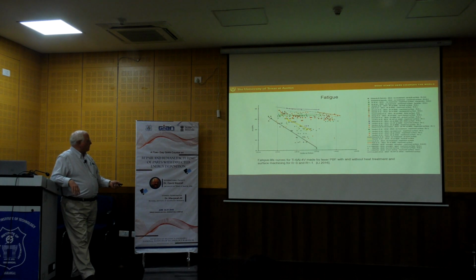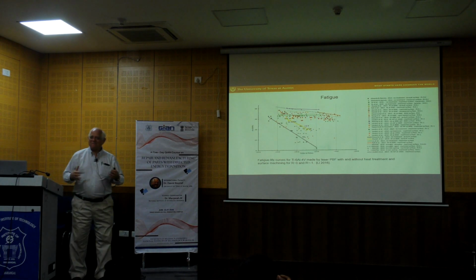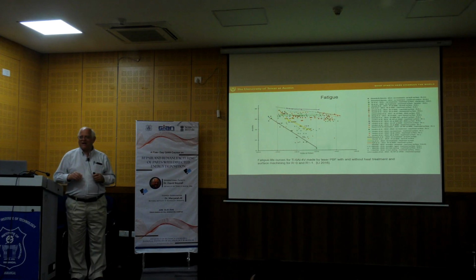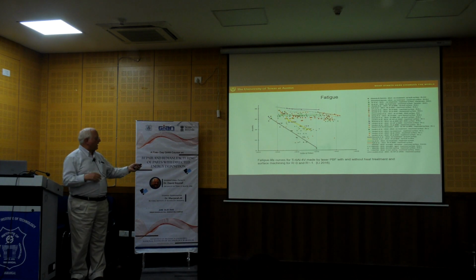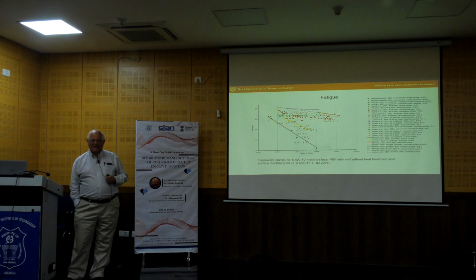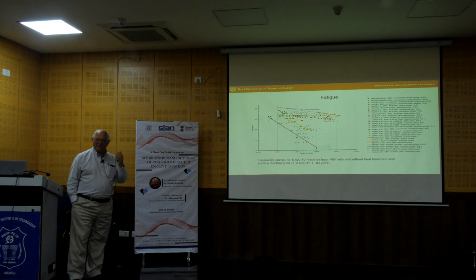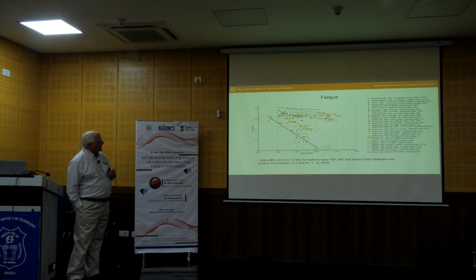This came from Lee in 2016. It's all titanium 6-4. In this case, it's all laser powder bed, but we'll get to see the same thing in DED. And it's with and without heat treatment. He accumulated the results from a ton of investigators. What we see is what I call a spaghetti on a wall plot, where the whole graph is just completely covered with data points, which typically doesn't have much value, but we can glean some things from this.